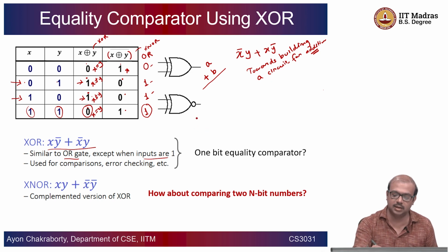Let us say if you add 3 and 5, this becomes 8. There is no carry forward. If you add, let us say 7 and 5, the sum is going to be 12. So, 2 remains in the units place and 1 is carried forward. In the jargon of designing these adder circuits, what remains in this location is called the sum, and what is carried forward is called the carry. Note that we are typically talking about binary numbers here.